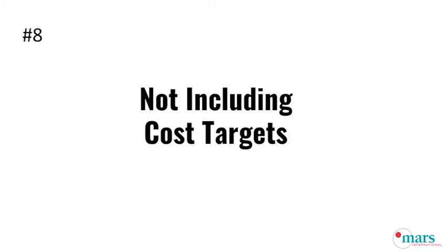Sometimes people are also just afraid that if they give a price target, they're setting the bar and saying this is what the price is going to be. And they don't want to leave themselves some room for negotiation or work and say what they can do. But having a cost target is going to be really, really important as early as possible in the product. It's going to guide the whole design. It's going to guide the selection of the components. And it's also going to guide when you're evaluating features early on.